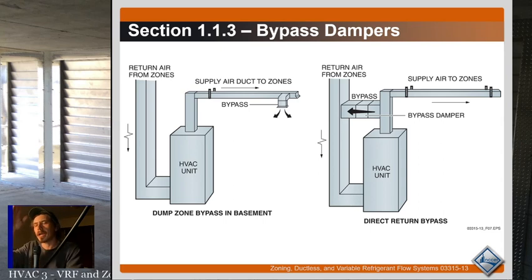So your amperage actually drops, and almost everybody invariably thinks that as the static pressure goes up, or as you deadhead something, the amperage will rise. Well, it will rise to a certain point, but if it's completely closed, that motor cannot do any work. There's nothing to move, so it goes to whatever the amp draw is for it doing nothing. So basically close to the same amp draw as if everything's wide open and it's just sitting there on the table spinning. That's the amp draw that you're going to pull, which is usually much lower than the rated amperage.